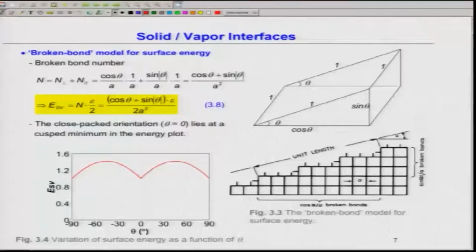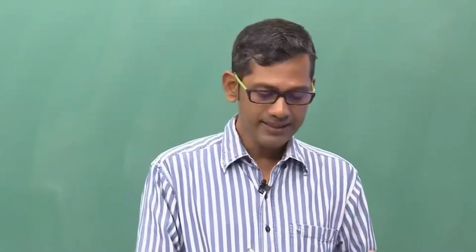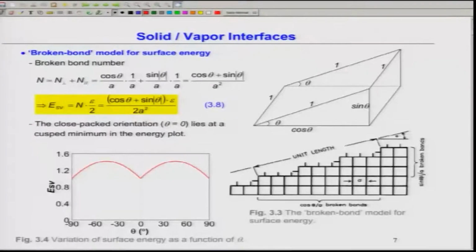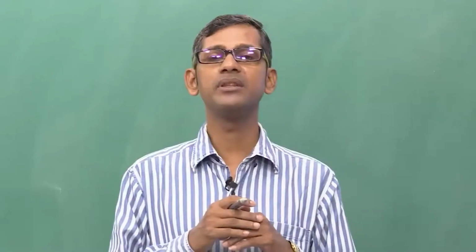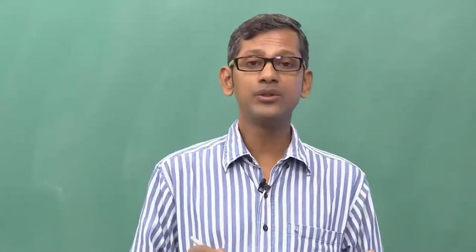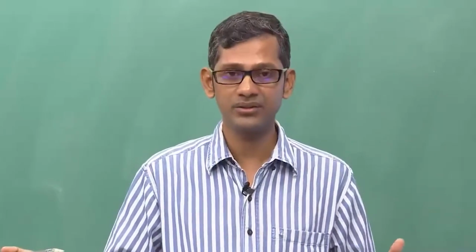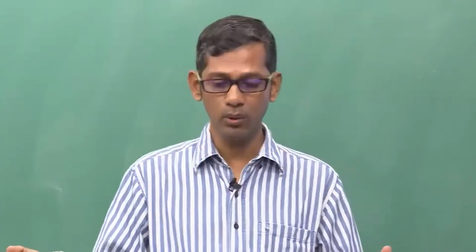So, therefore, these curves have minimum points, and these points are very important, because these are the points at which the surface energy will be lowest. So, if the system decreases its total energy, which is equal to G0 plus A gamma, the planes which will bound the surfaces must be the ones which have the lowest energies, because gamma is low means A gamma will be low.